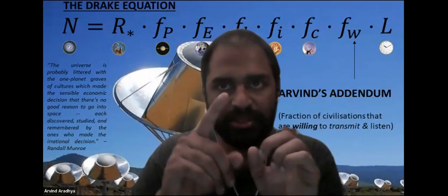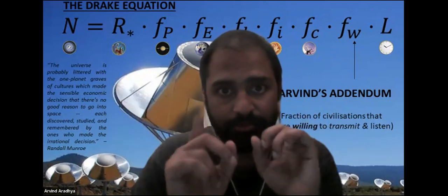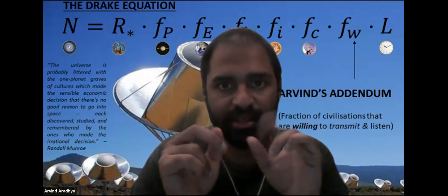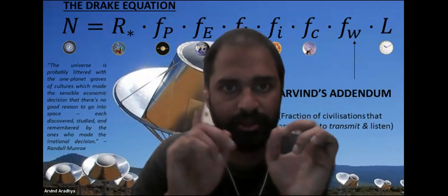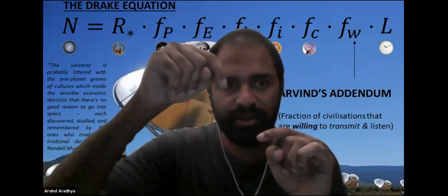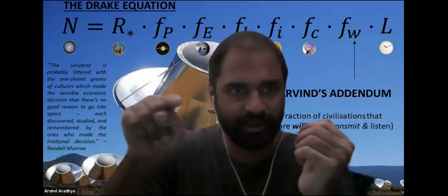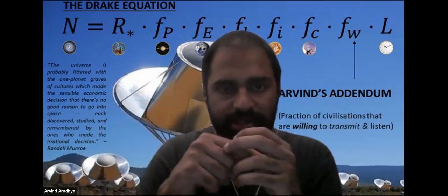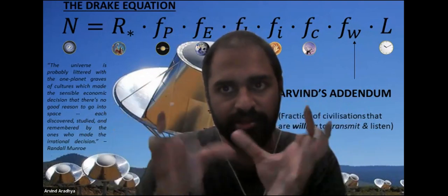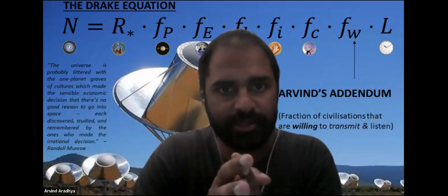So polarization is basically, if you've seen a 3D movie, you know what polarization is, because the 3D glasses have opposite polarization on the different eyes. So it's basically electric field oscillating up and down is, say, vertically polarized, but oscillating left to right is horizontally polarized. So if a vertically polarized signal is incident on a receiver that's only sensitive to horizontal polarization, that's fine. There's no interference that way.